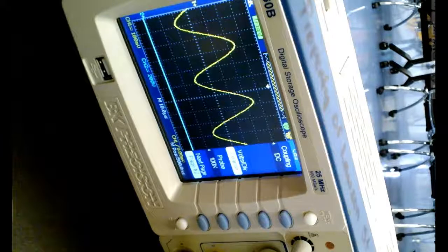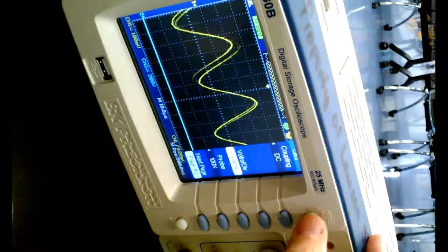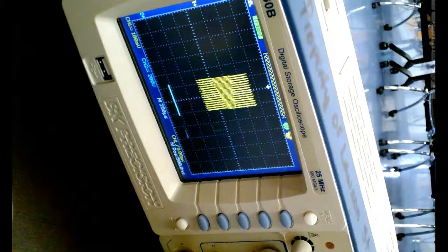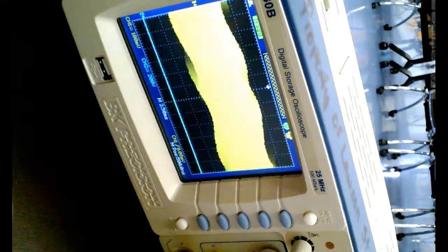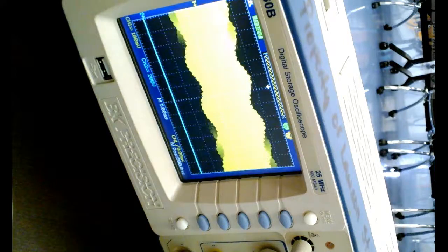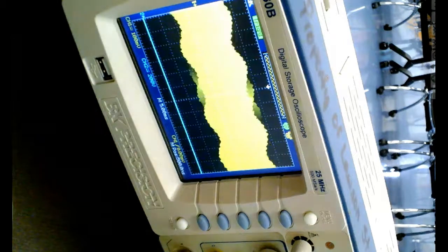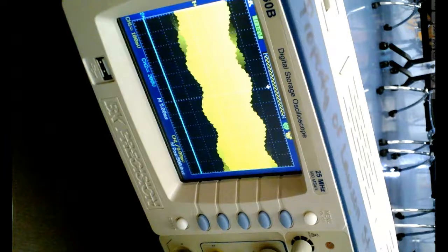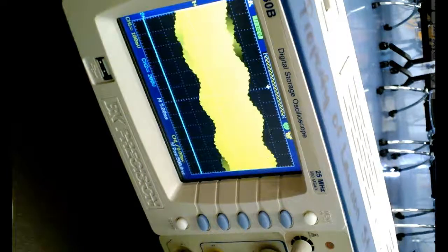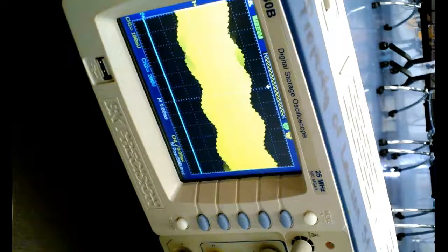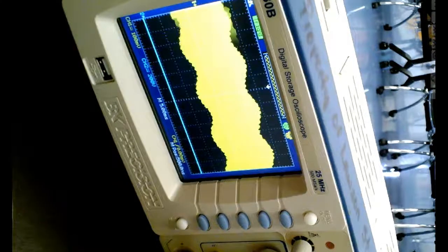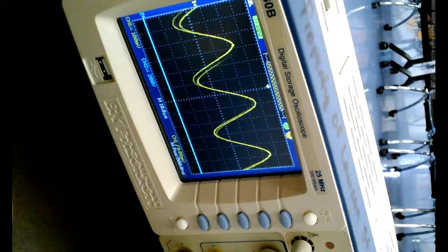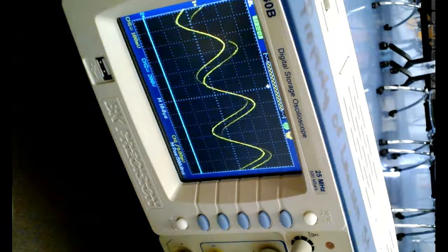Of course, undoubtedly I can't get the 60 cycle off of that. So that's why it's jumping, because it's picking up Alabama power. There's Alabama power right there. See the 60 cycles. We can't keep 60 cycles out. It's AC, right? You understand? And it's going to try to transmit through the what? Through the air. So we call this electric. We'd have to shield this a lot. I'm going to turn it up, but that's what's causing it to jump like that, is we're seeing the 60 cycles. But that's me right there.